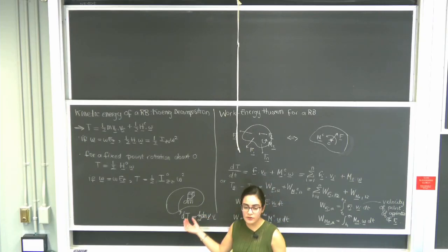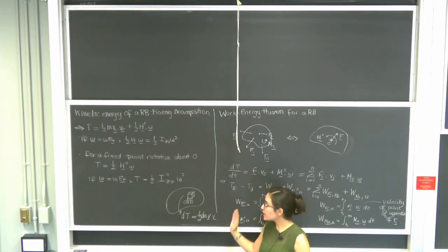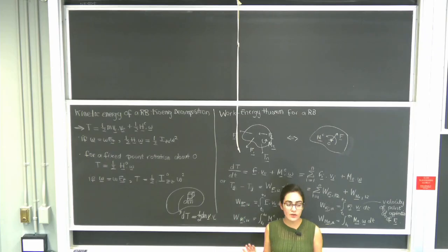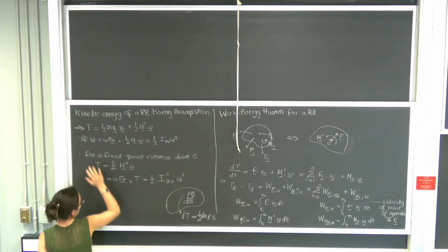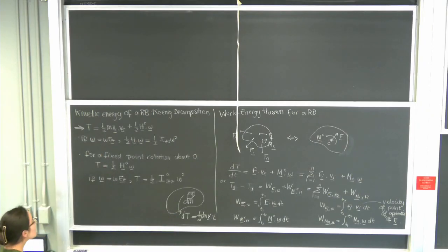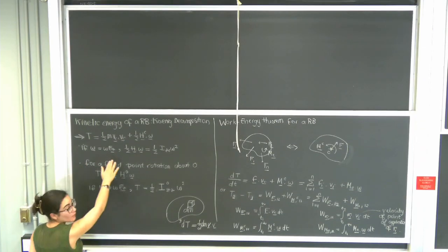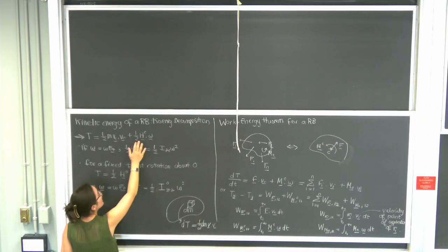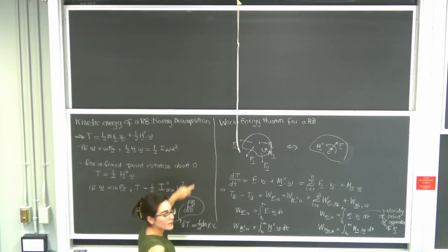So this is the kinetic energy of the differential mass dm, and the kinetic energy of the whole body is just the sum of the kinetic energies of all the constituents. It's kind of analogous to if you have a system of particles, the kinetic energy of a system of particles is the sum of the kinetic energy of the constituents. Okay? So this is how we obtain this expression for the kinetic energy. Now, in our particular situation, which is for this class where omega is along EZ, the expression for half HC dot omega simplifies. That becomes half Izz omega squared. Why does that happen?